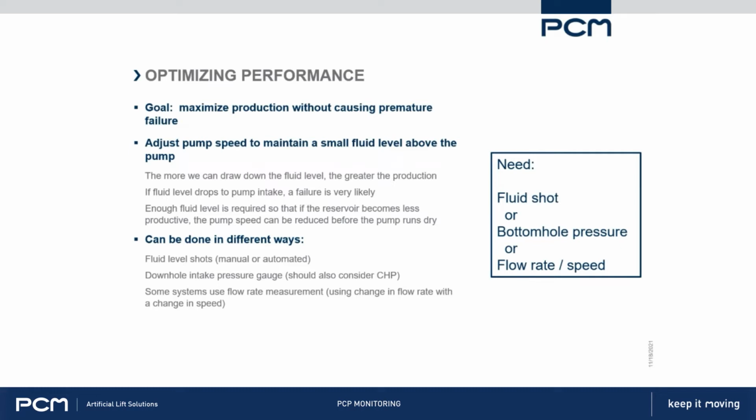Yes, if you see lots of fluid above the pump, you can speed it up, but you don't just speed it up and walk away. You speed it up and you take another fluid shot and look to see how it reacted. Maybe take a third one and see, is it stabilized? If it's not stabilized, if the fluid level is still going down, then you need to wait, because if you've sped it up too much, you could end up damaging your pump, having the failure.